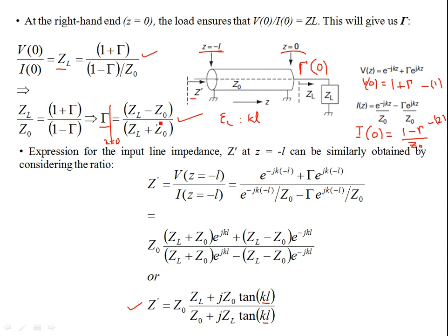Now, it also turns out that if gamma can be expressed in terms of the impedance, in terms of ZL and Z naught, at Z equal to 0, in terms of the load impedances and the characteristic impedances, then what is gamma at, let's say, KL? Well, for that you need to go down the line, okay, and you need to reach at minus L and see what is gamma KL, or what is gamma, let's say, halfway over the transmission line, KL by 2.